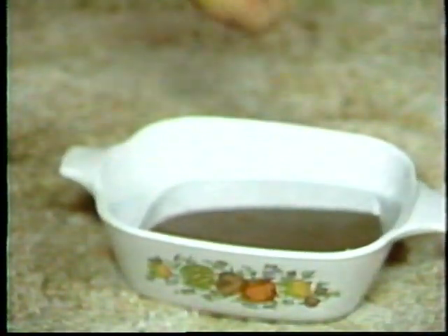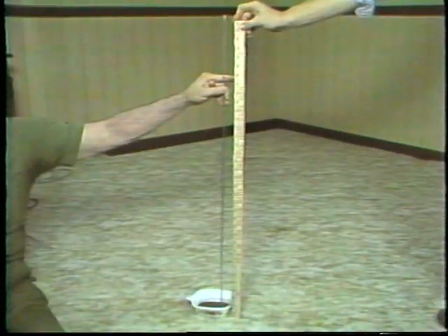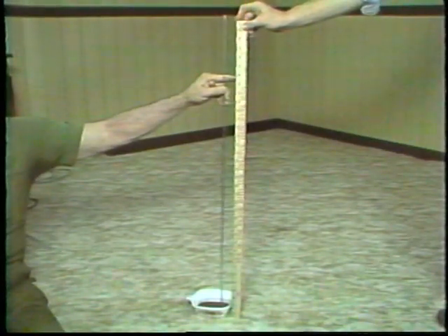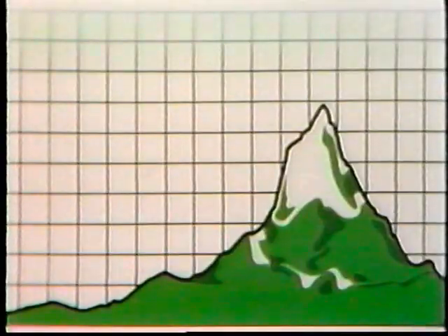Since the only thing that can balance the column of mercury is the pressure of the atmosphere on the mercury in the bowl, we can then determine, by the height in the tube, just how much pressure is exerted by the air which is piled upon the Earth's surface. As you can see here, the column of mercury is approximately 30 inches, which is what it's usually rounded off to. Actually, it's 29.92 inches at standard conditions and at sea level.